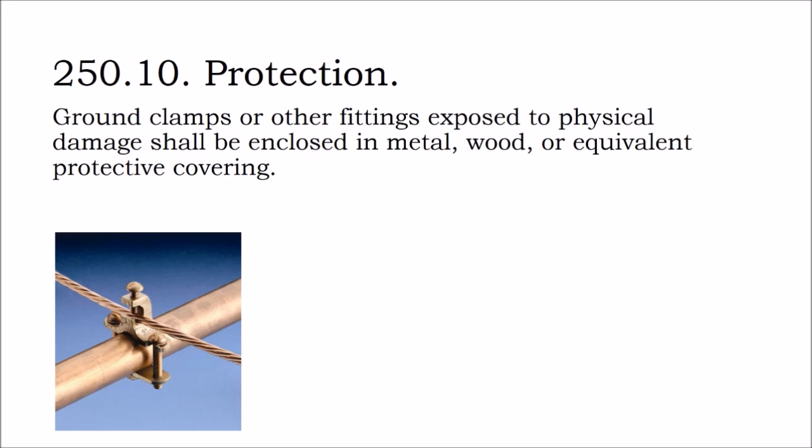Sometimes you need heavy equipment to install them. About 3/4 of an inch wide, with a copper coating. What it's intended to do is get some resistivity between your grounding system and the earth. Just sitting on top of the earth may not ground your building.